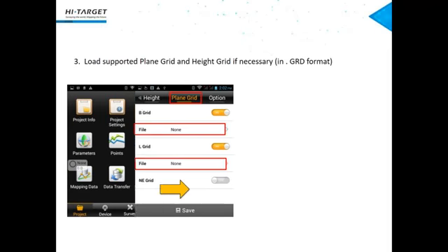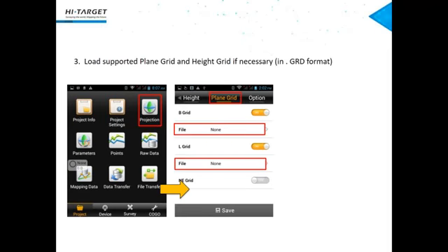So third, some surveyors may also need to use a geodetic file in their coordinate systems. So don't worry, HighSurv supports that. Just press a projection icon and go into projection setting to set some details of the coordinate system. You can choose to set height fitting and plane geodetic, which includes C grid and L grid as pictures below.